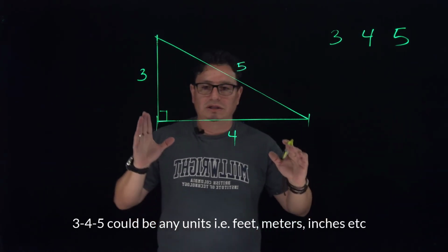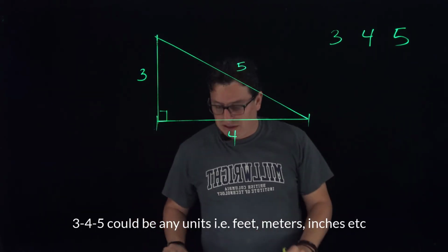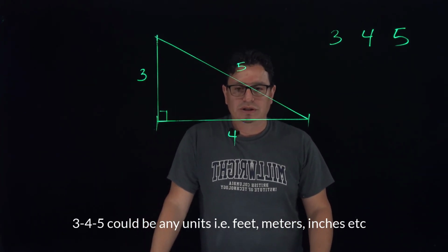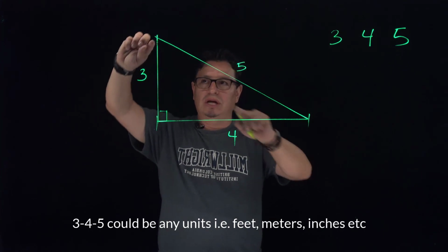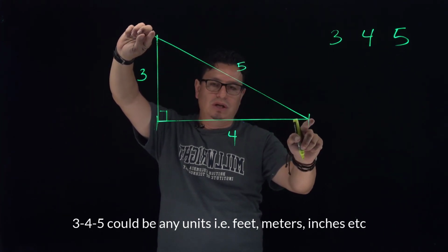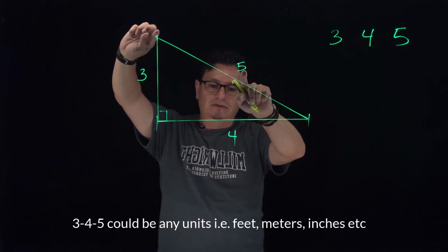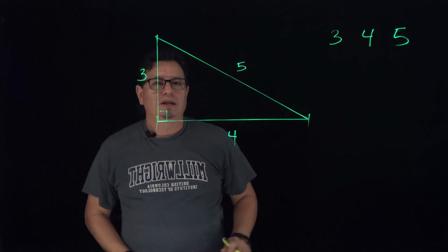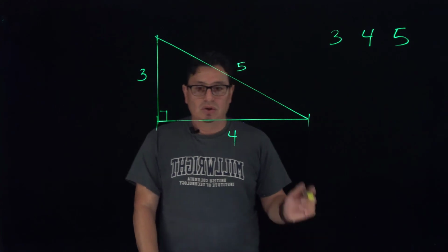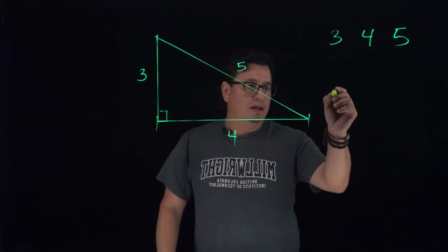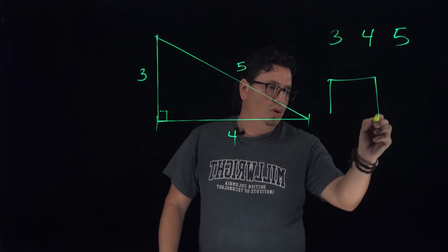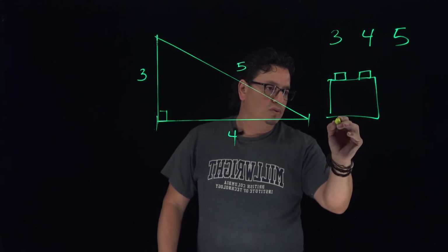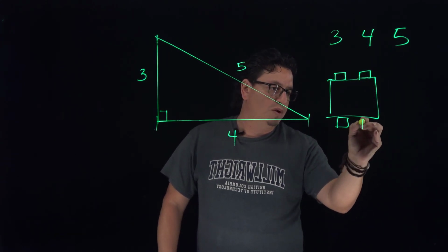When you're out in the field, sometimes you have to adjust your lines. If you're using chalk line, or different tools out there, you might have to adjust it so that your measurements from one side to the other are exactly, in this case 5, this case 4, this case 3. So again, finding your right angle, 90 degrees. If we were out in the field and you have the pump or the motor, this would apply the same way as what we showed you in the previous videos.